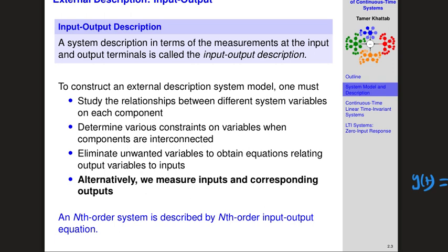Remember when you studied, did you study filters in your electronics? Yes. Right? So filters, if you have RC and then another RC and then another RC, that's a third order filter, right? If you have more of those, then you have higher order filters and so on. So it depends on the number of critical components that really affect the input-output performance of the system, other than simply scaling them. It differentiates, it integrates, and so on. Not just multiplying the value by a constant.